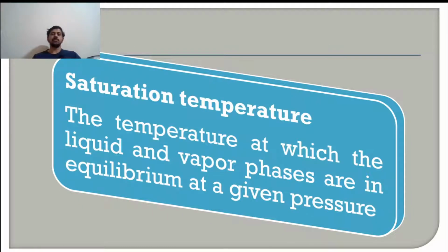Similarly, saturation temperature is the temperature at which the liquid and vapor phases are in equilibrium at a given pressure. So both are dependent, temperature as well as pressure. At a given pressure, when two phases are in equilibrium, that is the saturation temperature. At a given temperature, when two phases are in equilibrium, that is the saturation pressure.